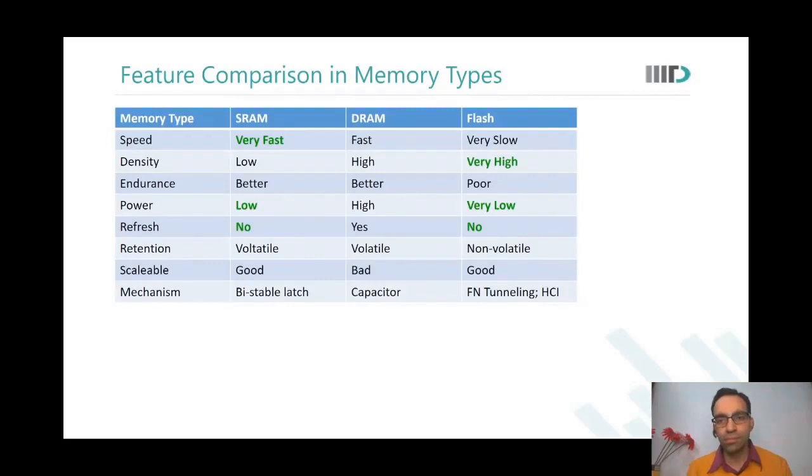So can I say that the PROM is storing the information of like which cell is working properly and how many extra cells are available to us, so that it can allocate in the future? PROM will not do those evaluations itself. PROM will only store the location of the failing cell, for example. And now there will be some logic on the chip which would say, okay, if this location is failing, let us redirect the addressing to that other location.